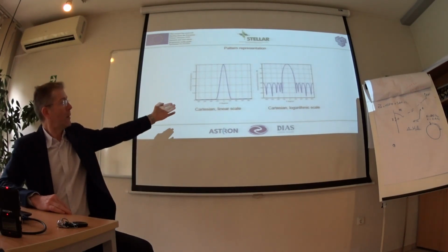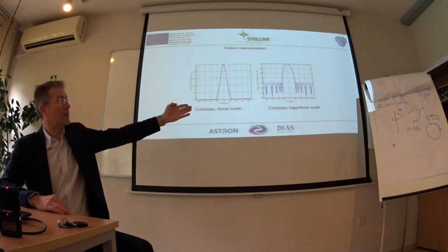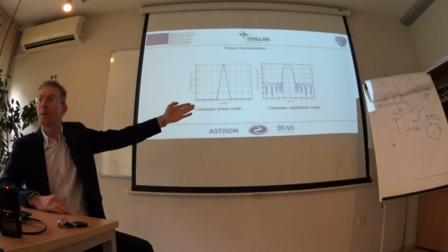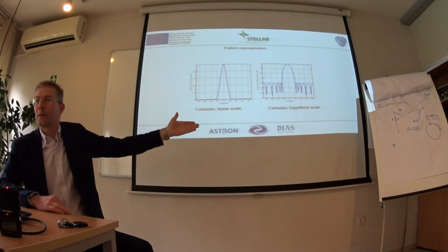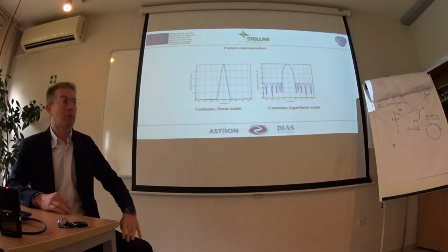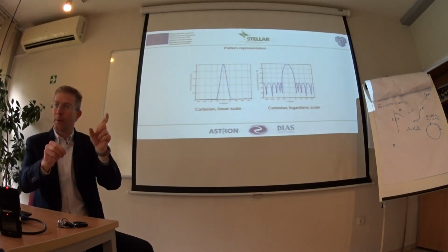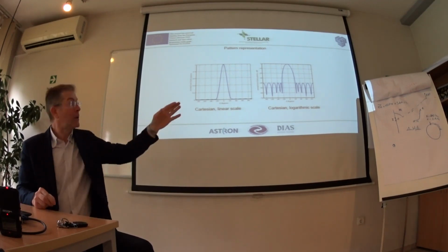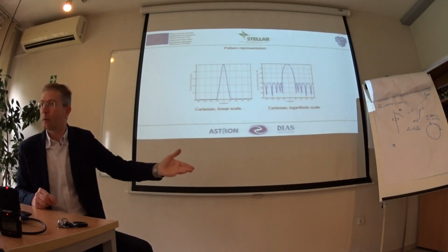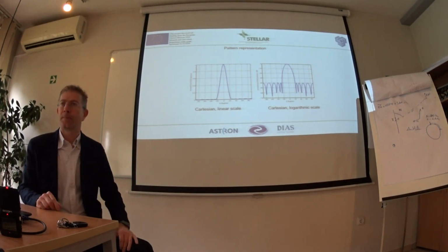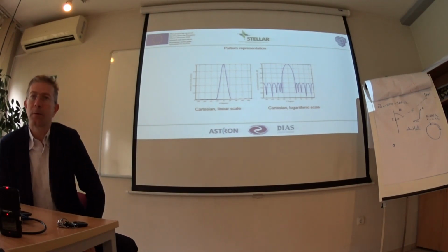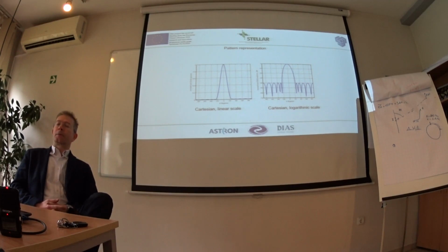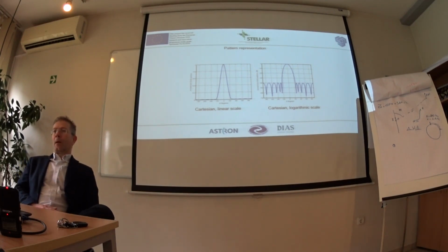And that's why this Cartesian logarithmic scale is the most used way to represent antenna pattern. That's how they are specified. So you can easily grab a ruler and measure the values. You see the small numbers clearly and make any necessary measurements, etc. Logarithmic Cartesian.